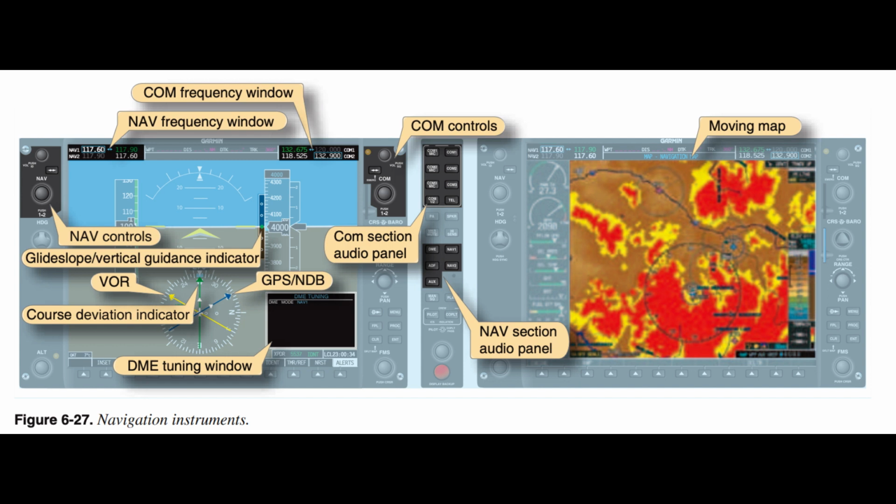By utilizing these four steps, pilots can better manage the attitude of their aircraft. One common error associated with this process is making a larger than necessary change when a deviation is noted. Pilots need to become familiar with the aircraft and learn how great a change in attitude is needed to produce the desired performance. Applying the four-step process.